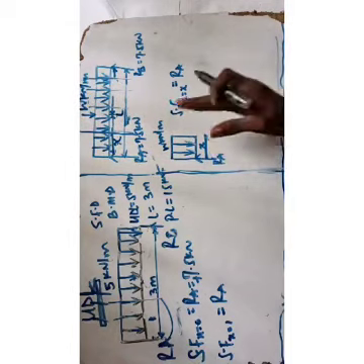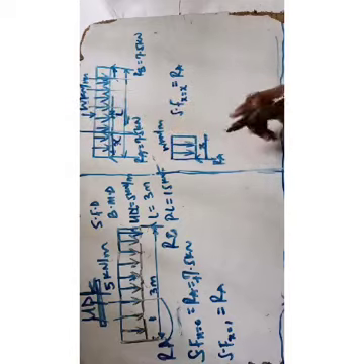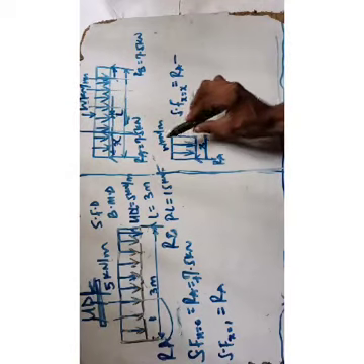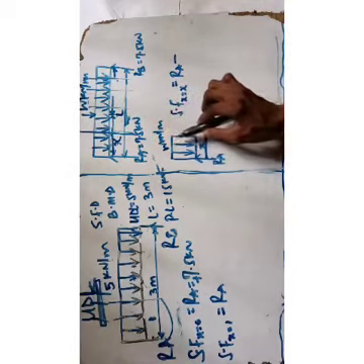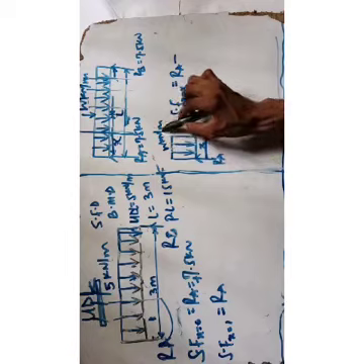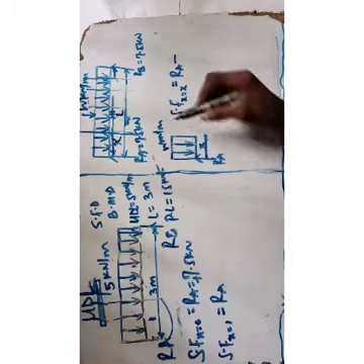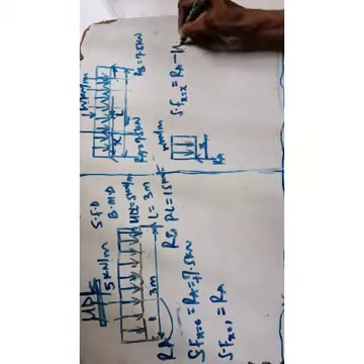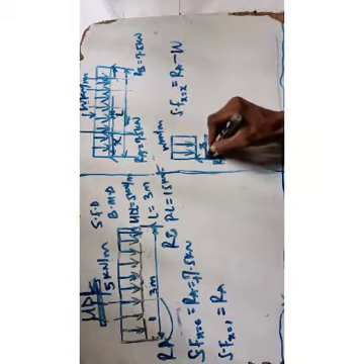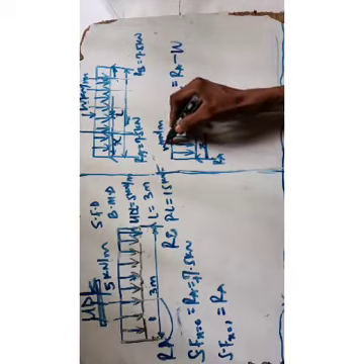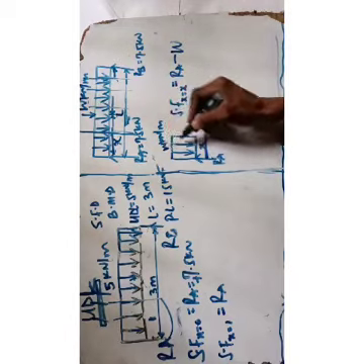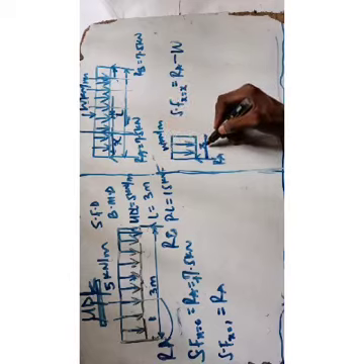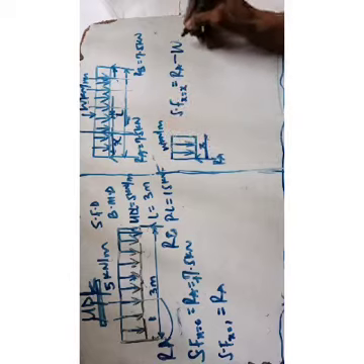So if you want to take the shear force, you would section it out. Then we have RA minus this W kilonewton per meter. You would first of all convert to point load. That will be RA minus this weight times the length. That is the total length. So this weight here, the length we are considering here is this X. Now it will be W times what? X.